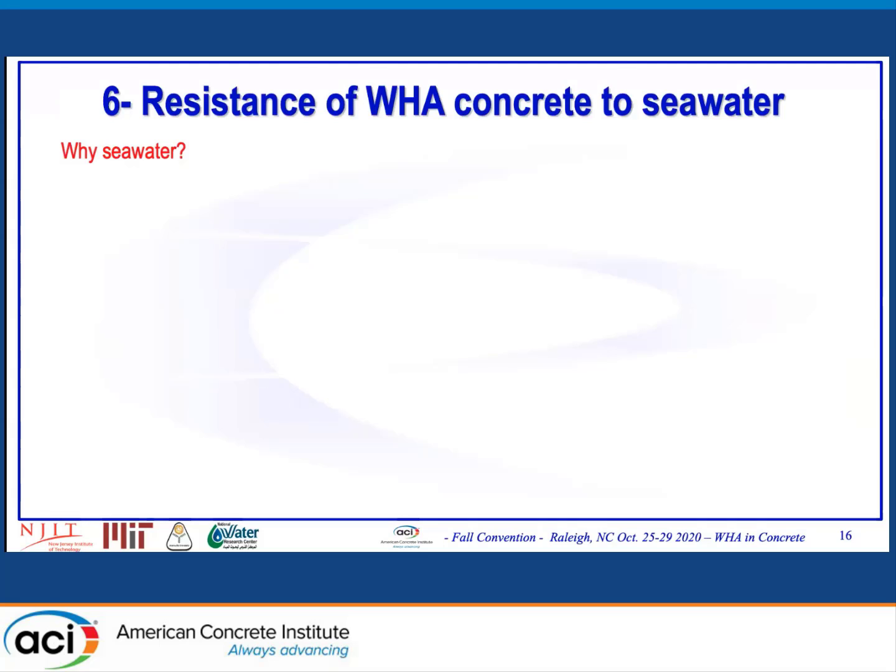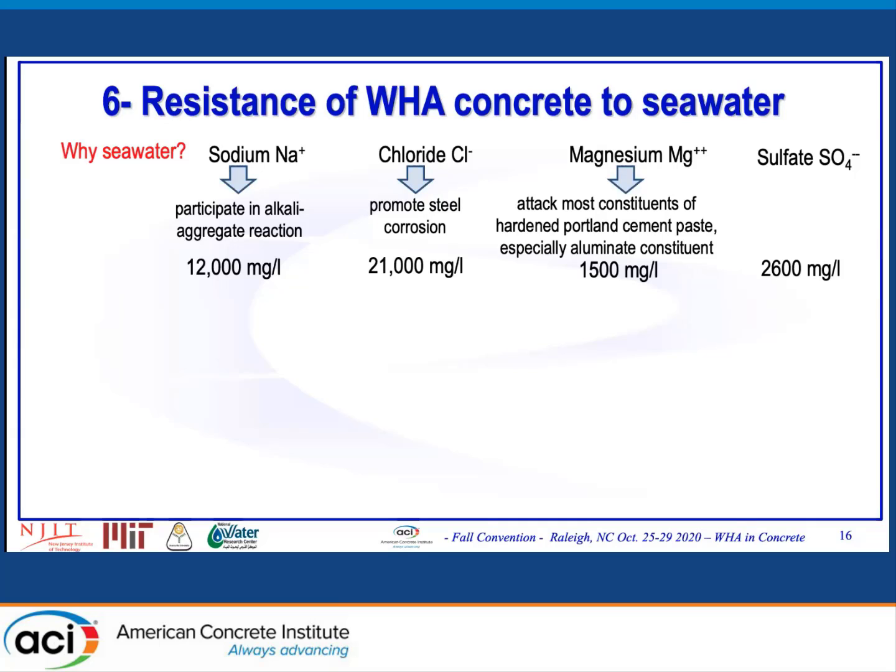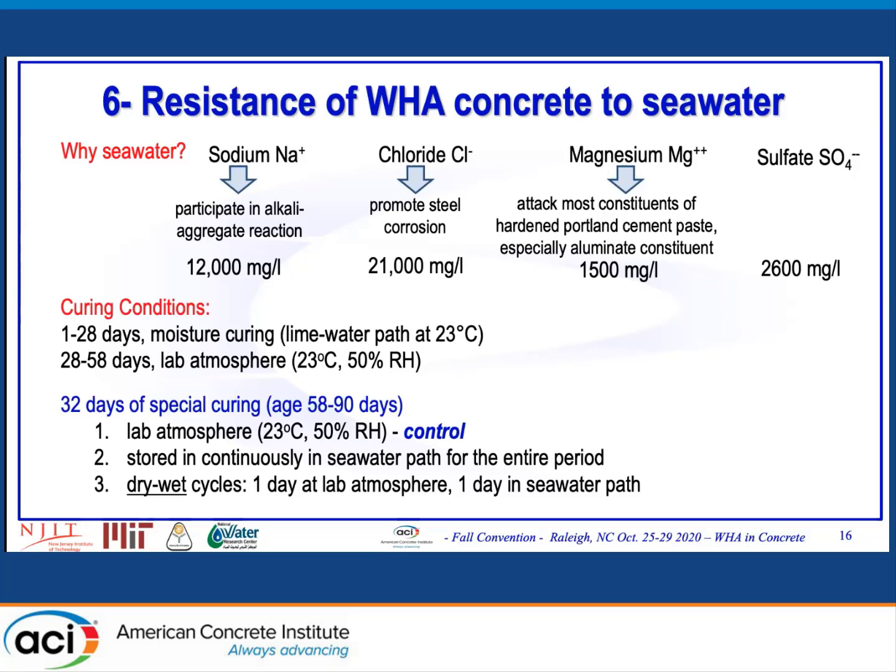So the second part is the seawater resistance. I selected seawater specifically because it has more ions, not only one ion, so it has multiple ions. And again, I cured the samples during the first month in normal curing, and the second month I left them at lab temperature. And after 2 months, I started subjecting them to seawater.